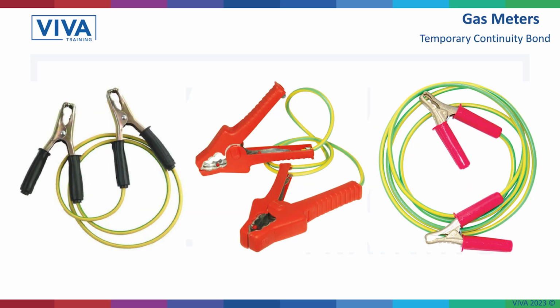If we're removing the meter, what we need to do is put a temporary continuity bond across it. Because if we remove that meter, we're breaking that circuit from the inlet to the outlet. The meter is across that inlet to outlet, so we're putting a continuity bond on to maintain that circuit. Because if we remove that, we could get a spark. Even though we've tested it, we want to make sure we do the job properly.